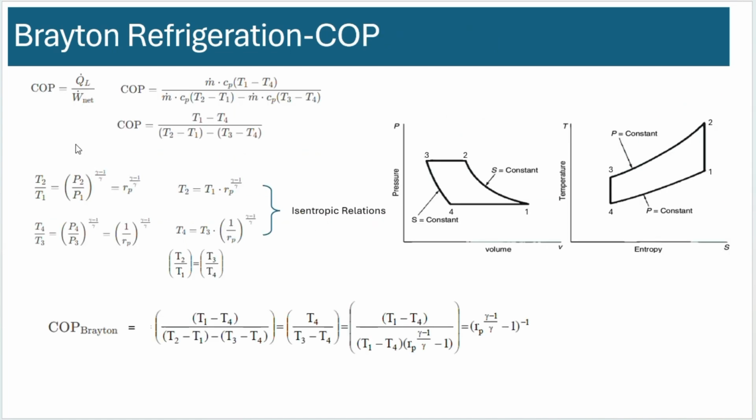And overall, the energy ratio, or the efficiency ratio known as COP, could be written based on Q_L, which is the output, and W_net, okay? So overall, you could get an equation like this as a ratio of temperatures. You can rewrite them in terms of pressure ratios, where there are only two pressures in the system, P2 and P1, high and low.